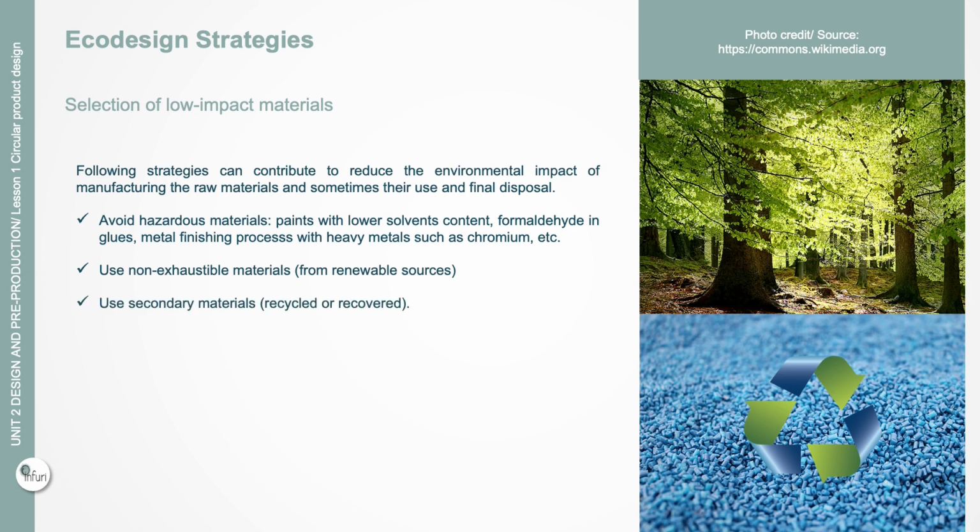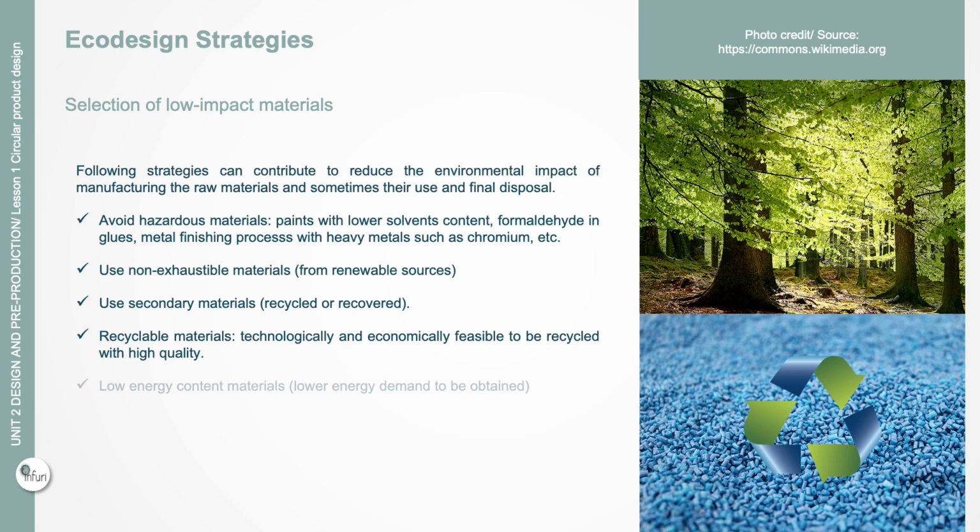Check the selected materials, and also how they are integrated in the design, are nowadays recyclable. Finally, there are materials that need a larger amount of energy to be obtained than others, so try to collect this information and select those materials with lower energy content.